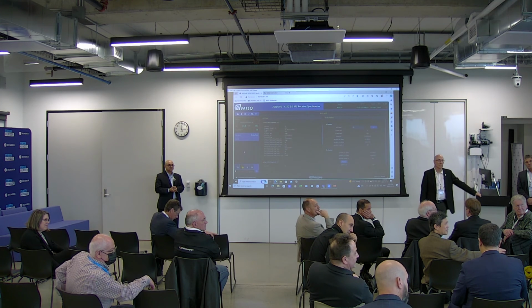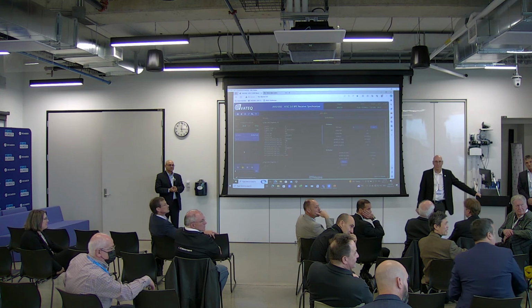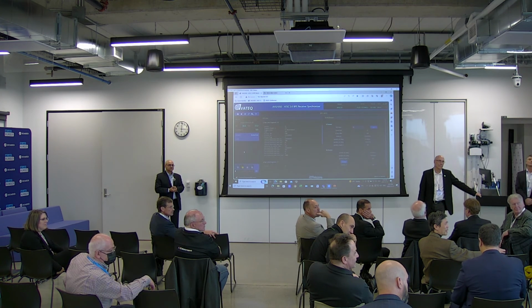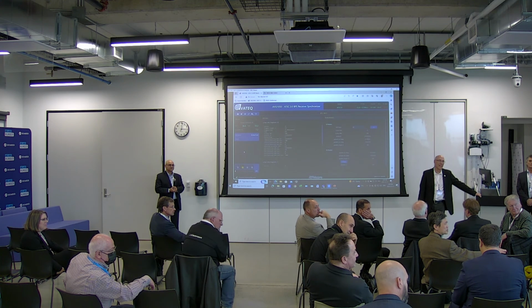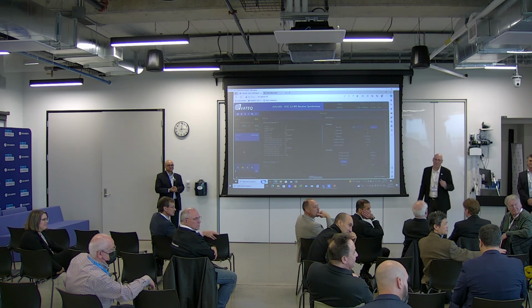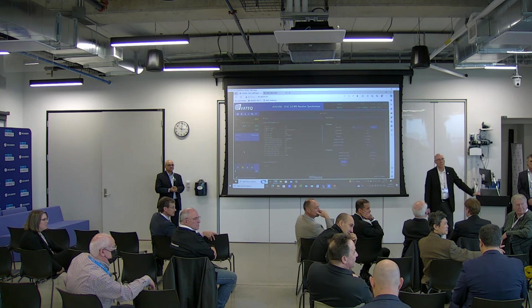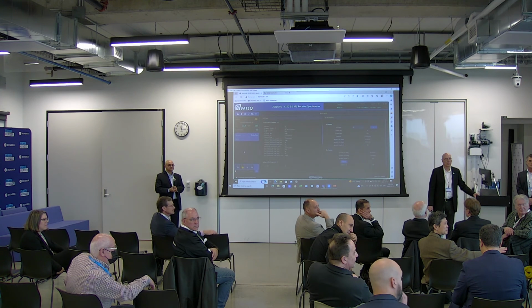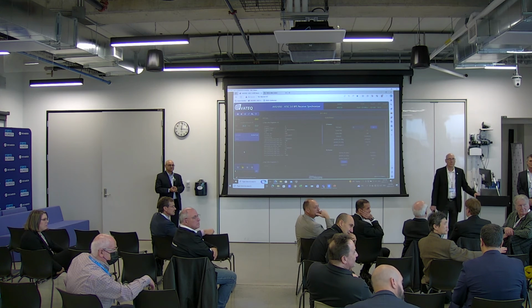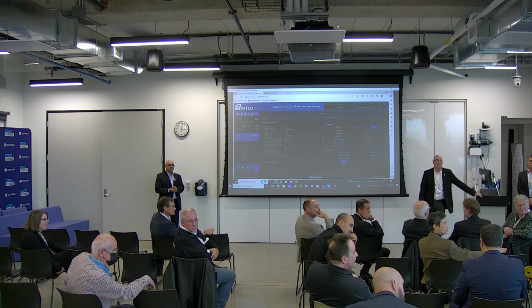If you're getting 3 meters or you're aiming for 3 meters, then what's out at the tails? What's out at the tails might be 100 meters. So if you're talking about car lane level navigation, unless you're in Australia, out in the outback, that's not how wide a lane is. So the targets that we have for GNSS and PNT, I do want to point that out to everybody. They're orders of magnitude different than I think what people are thinking of when they take their Garmin out for hiking. And this is coming now directly from the constellations or from service providers. And we've been doing this for a while. This isn't new.